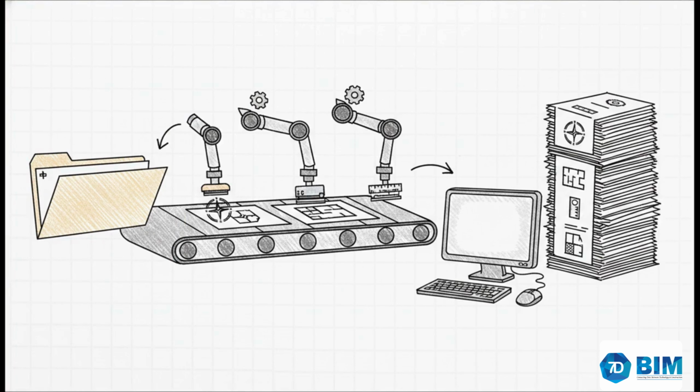Let's talk about standardizing your output. Out of the box, the software is going to use cardinal directions for elevations, or just super basic names for floor plans. As a BIM manager, you need to rename these to match your firm's specific conventions, like calling it Level 1. You want to enforce view scales before a user even opens a sheet. Utilizing sheet manager tools and templates to auto-generate standard views eliminates literally hours of mind-numbing repetitive labor. You want all that tedious setup completely done before the design team even logs in.